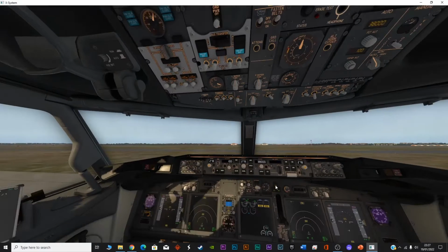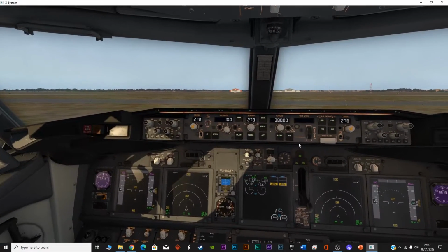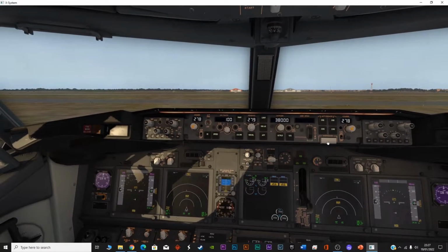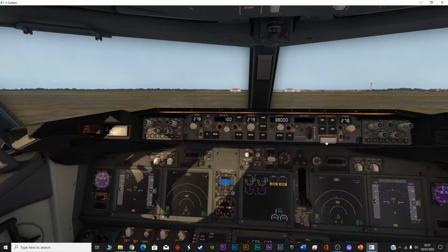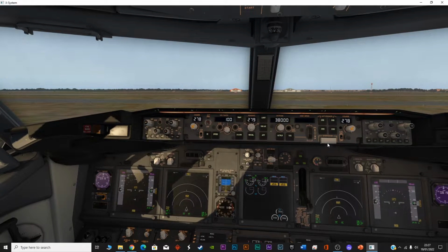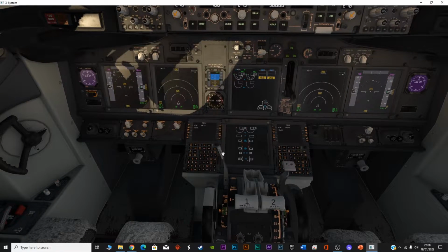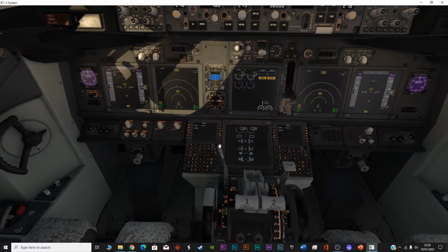And just make sure that the autopilot is off, and its disengage button is up. Otherwise, if you disengage the autopilot, it drops down. So it's up, and all the options in the autopilot are off. Speed brake is off. Check.